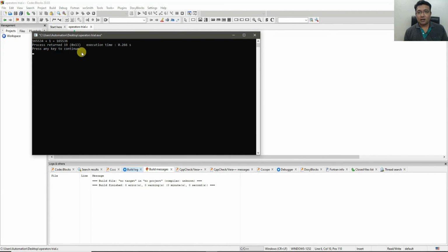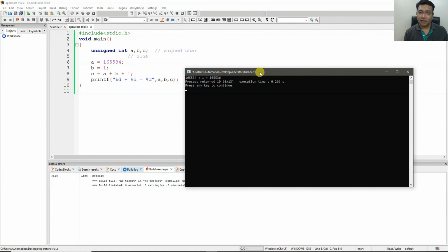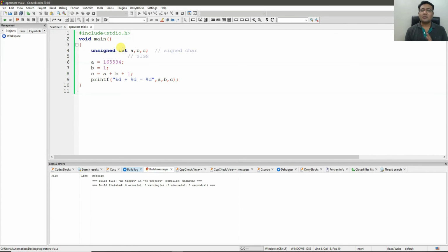But since we are trying to understand things from an embedded perspective, understand that on embedded systems, the int variable has a 16-bit value. If you go to a higher version of microcontroller, like 32-bit ARM controllers, then you will have to look into the data sheet of those. Most probably, 32-bit compilers will also implement int as a 32-bit value, and the same limitations will apply.